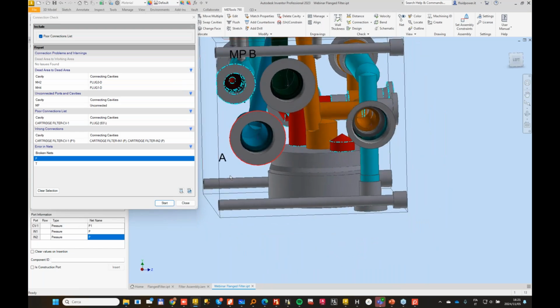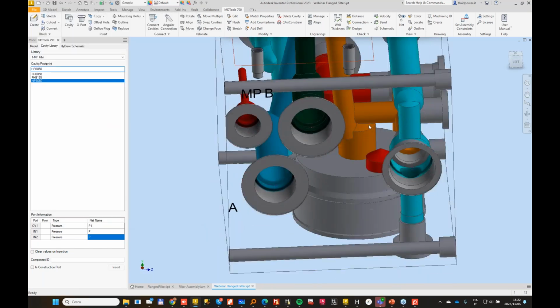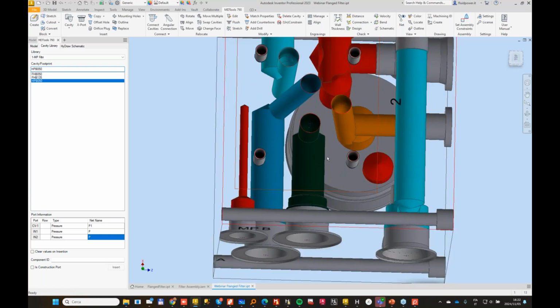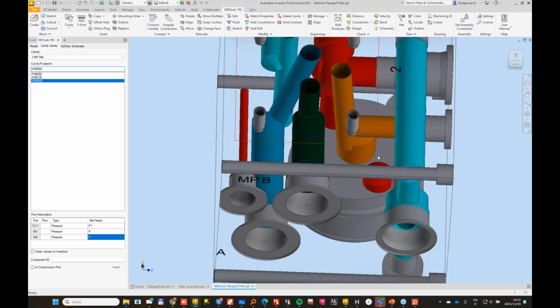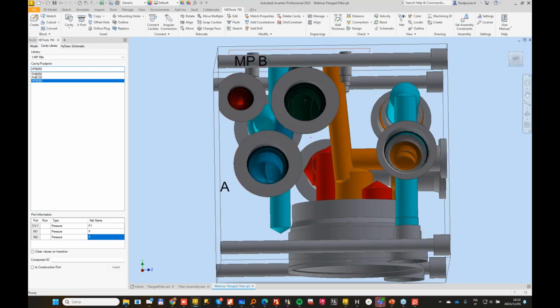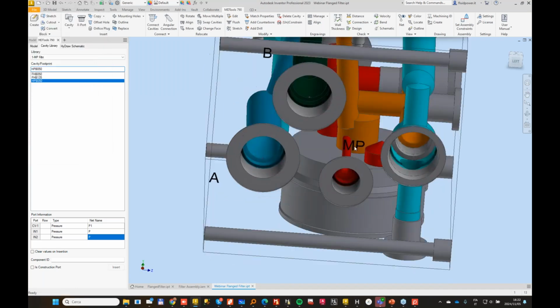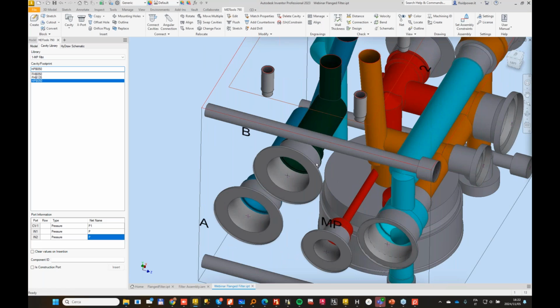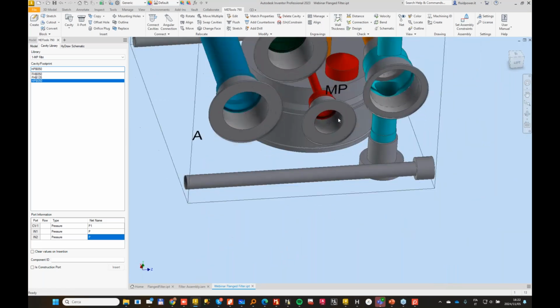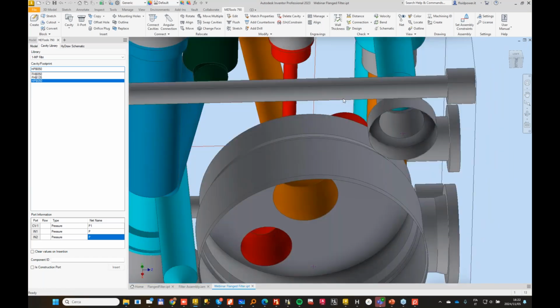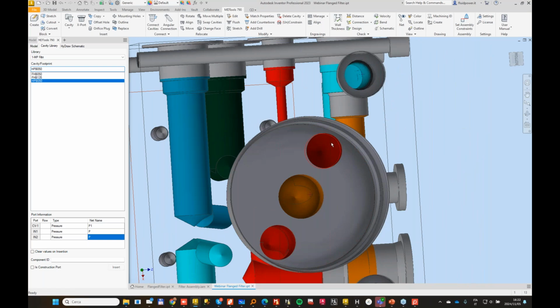Now, in my case, I will do something tricky. I'm not expecting to enter with the pressure in another position. I will use it here just to read my pressure. Since I have a test point, and when the oil is inside the filter, the pressure will be the same on both sides of the cavity, I can use this drill, the red drill, to connect with the test point.